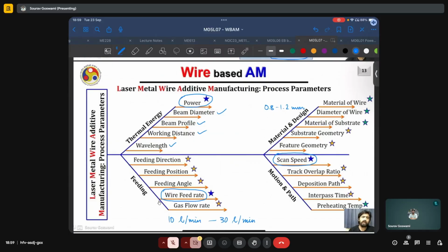Secondly, we may be working with materials such as aluminum or copper, which are notoriously difficult to print with such laser-based techniques. This may be because of the high reflectivity or the poor absorptivity of these materials. But by preheating them, we can overcome these features. That is, with increasing temperature, we can make them more absorptive, and so it may improve the print quality.